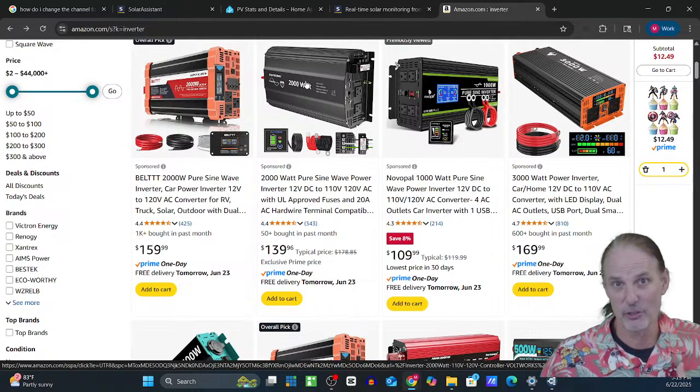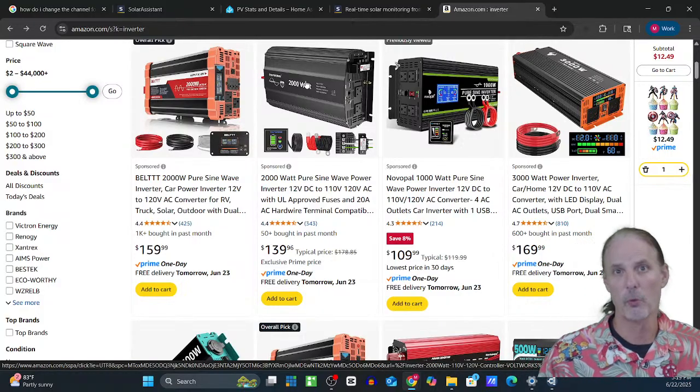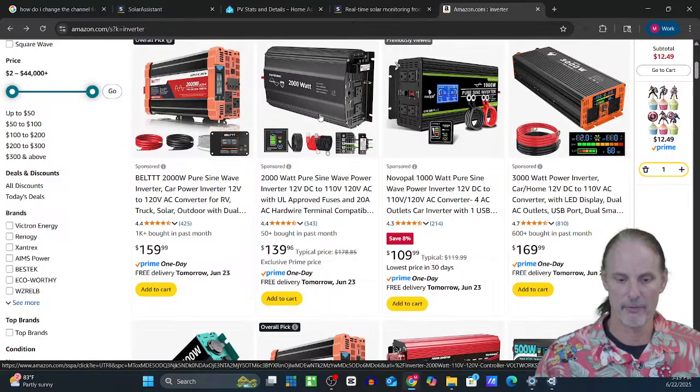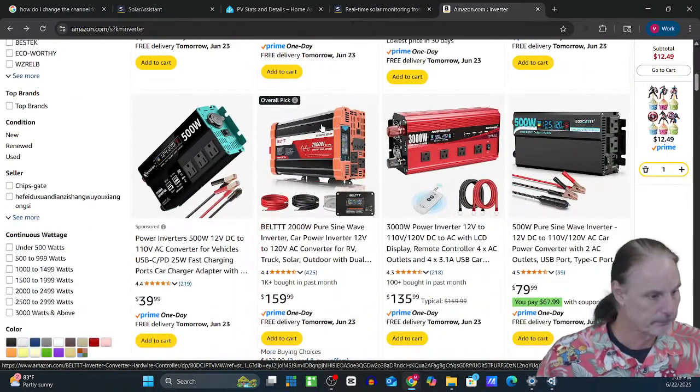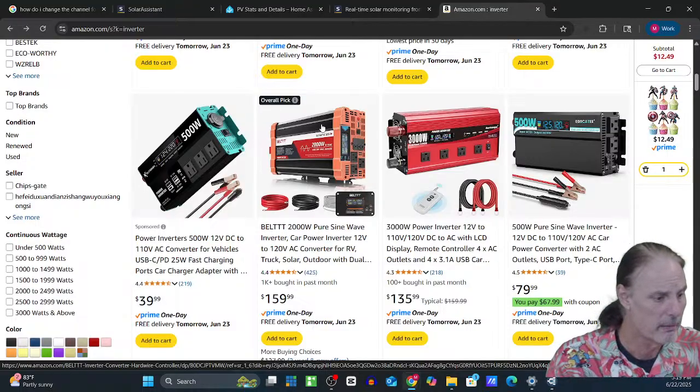And in my case, I'll usually leave a 40 or 50% buffer just to be sure that I can handle the surge with the normal wattage plus a bit of a buffer on top of it. Hopefully that answered the question for you, Mage, and you got what you needed out of that.